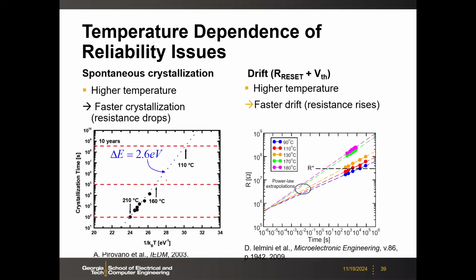But also in the phase change memory, there is a unique drift behavior, which is somehow opposite. The resistance in the low resistance state also tends to go to higher resistance states. You see that here, the resistance tends to go up. This is due to some relaxation behavior.